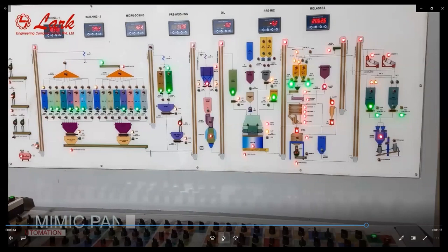So we did audits in feed mills. What we observed, not in each and every feed mill, but in a few feed mills, is that in the night shift the pellet operator generally runs the pellet mill at 80 or 85% efficiency to avoid the overflow of the cooler siren system.